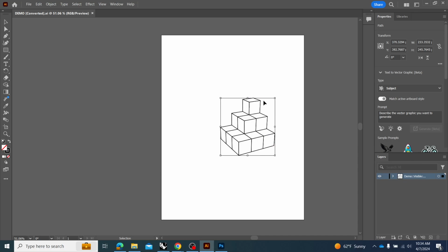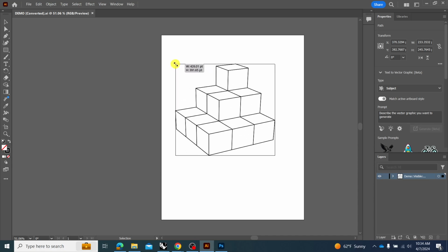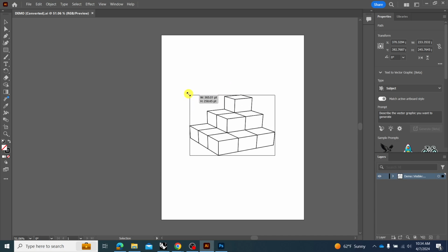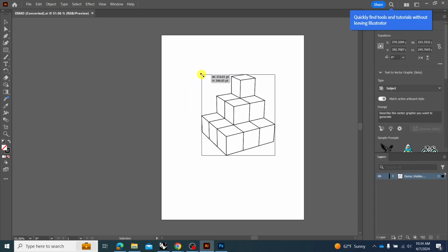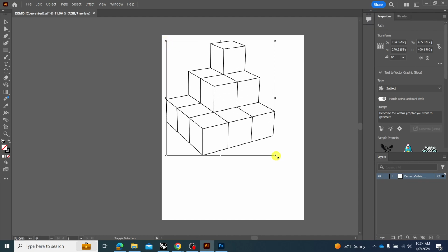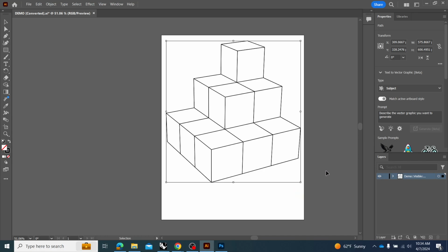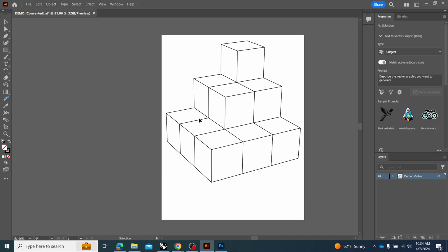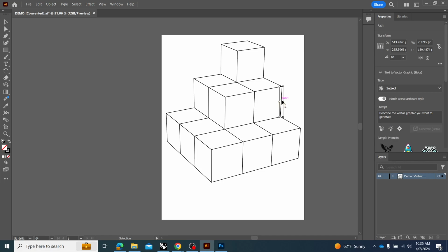So in order to stretch or scale this, we can drag this shape handle, but we can see that now it's losing its proportion, which we need to maintain to match with our image. So what we can do is hold Shift, and we'll maintain those proportions. Okay. Now what we can do is start to manipulate the line weights and everything like that.